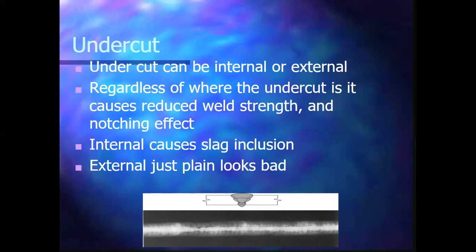The solutions to that are just welding a little slower, hanging out a little bit longer if it's a vertical weld, and filling in everything you removed with the arc, because the arc kind of cuts away material and then fills it back in with weld material. That's how we get the good penetration. That's how we know we've got good penetration.